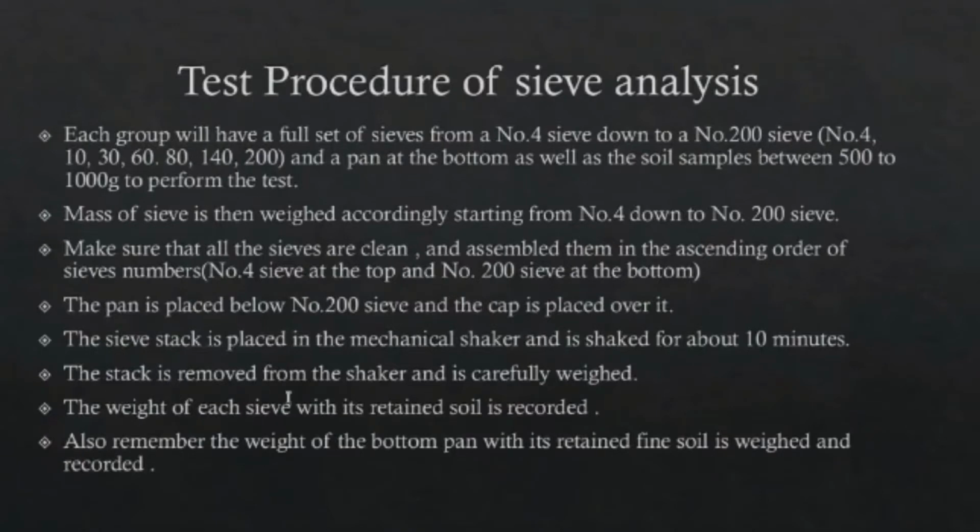The stack is removed from the shaker and is carefully weighed. The weight of each sieve's retained soil is recorded. Also remember the weight of the bottom pan's retained fine soil is weighed and recorded.